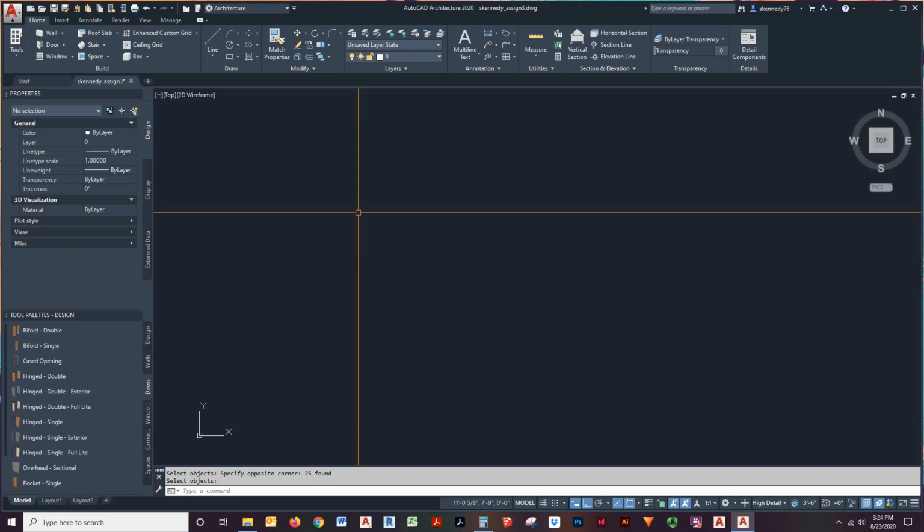So if you do find an architectural set of drawings and it's printed, you can usually have local printing companies scan it in at full scale, and then you can use that digital file and insert it into AutoCAD. And I would recommend that you tell the printer company to scan it in as a .png or a .tif, TIF or TIFF. That'll make sure that the file will not get distorted or give you any trouble later on.